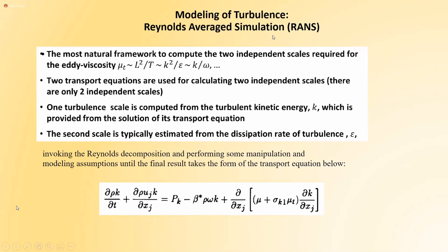Okay, modeling of turbulence, Reynolds average. We connected here that the eddy viscosity is a feature of the flow, not a feature of the fluid, unlike the dynamic viscosity.